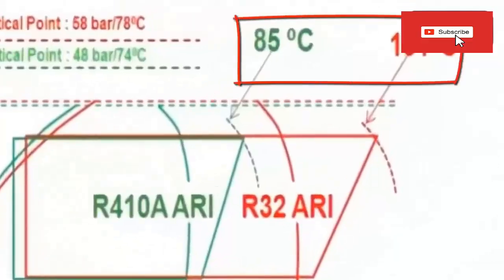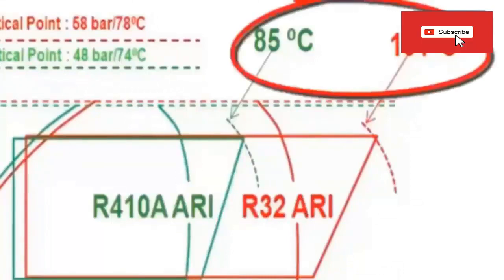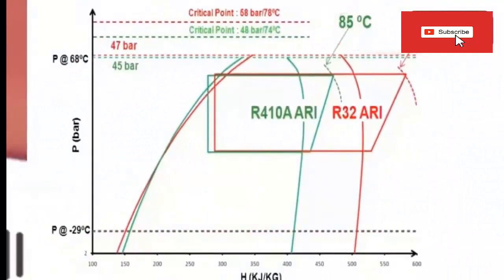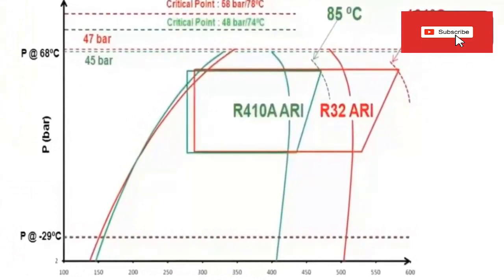We can see that the discharge temperature of R32 in this example exceeds that of R410 by 16 degrees Celsius, and this actually happens very frequently. From this we can conclude that if we update a unit that is working with R410 refrigerant by now adding R32 refrigerant, the compressor will have higher discharge temperatures, which will significantly shorten the useful life of the compressor. In the equipment specially designed for R32 refrigerant, this problem of high discharge temperature is dealt with, either with cooling strategies or with different oil viscosities, so that the compressor does not have problems.